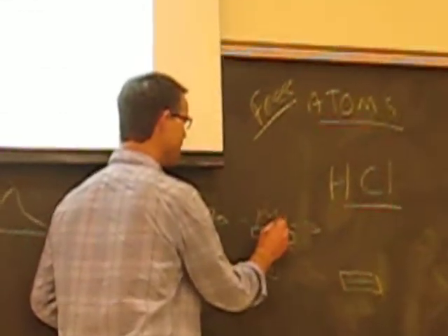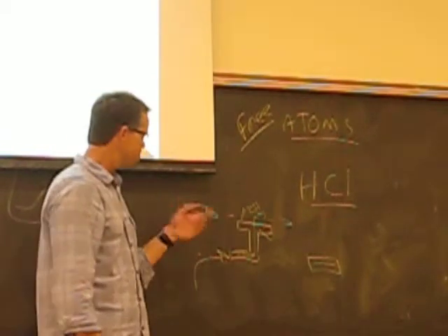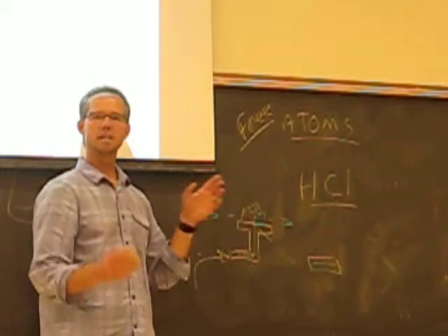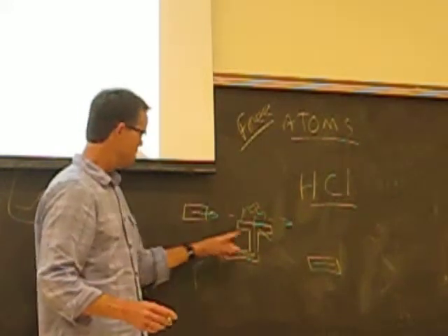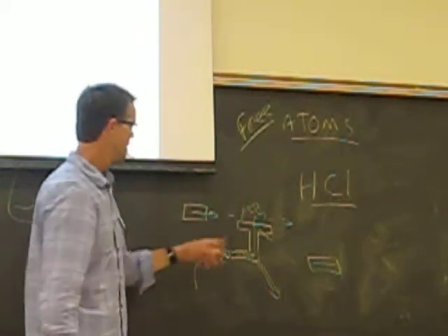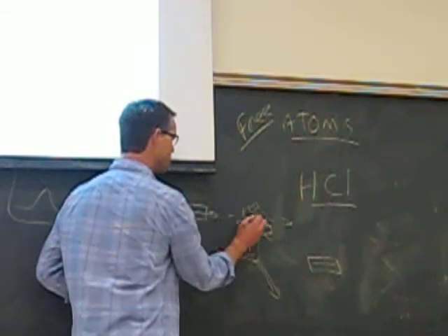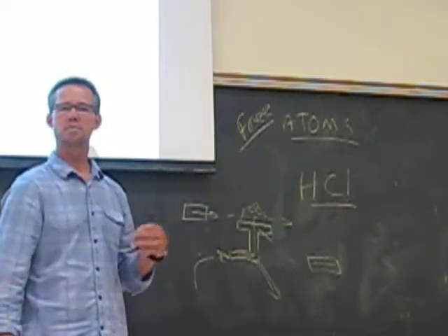And the heat from that flame, then the sample is constantly passing up and away. And maybe about 1% of the liquid you introduce into the instrument makes it up here, and the rest of it drains away into a drain. And as the sample is passing through that light path, it interacts with those photons.